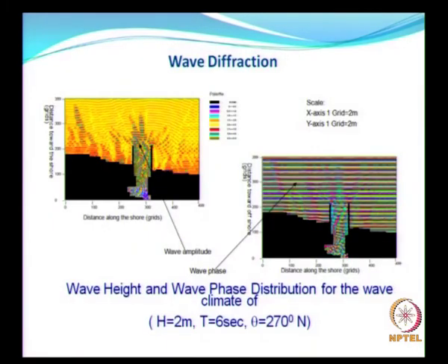This is what we have done in our laboratory, in our department, wherein on the left side you see the wave height contours, and on the right side you see the waves penetrating directly, as the waves are approaching more or less normal to the shoreline. So, this picture would give us the extent of tranquility and what wave energy or wave height you would have, and whether it will be within the permissible limit when a vessel is traveling, etc., when the vessel is moving.